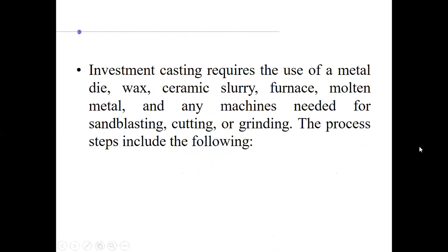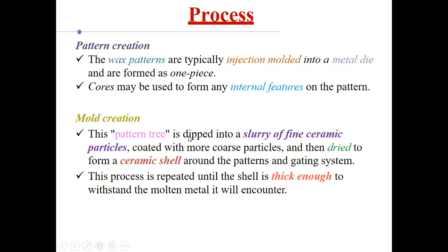Okay, let's see these steps. As I was talking about, the first step is pattern creation. The pattern material will be wax, injection molded into a metal die, and you will form it as one piece.